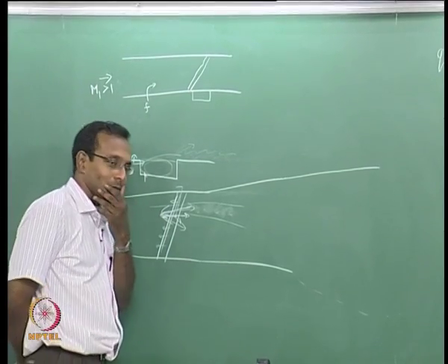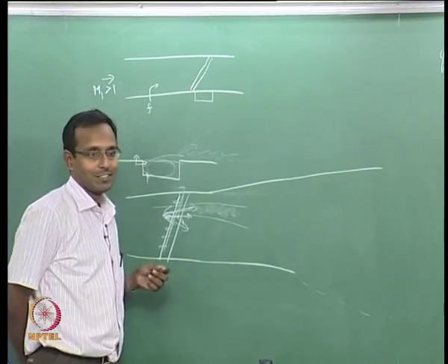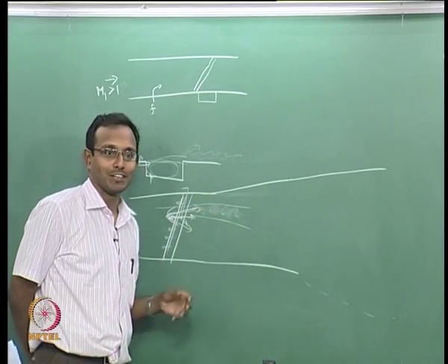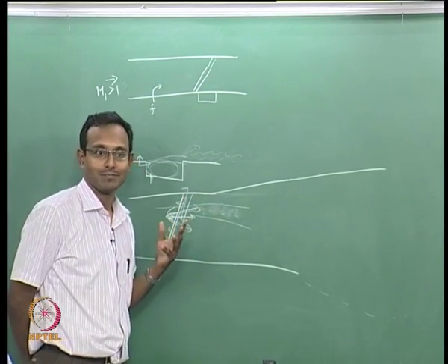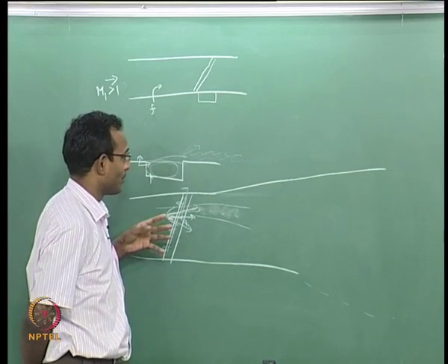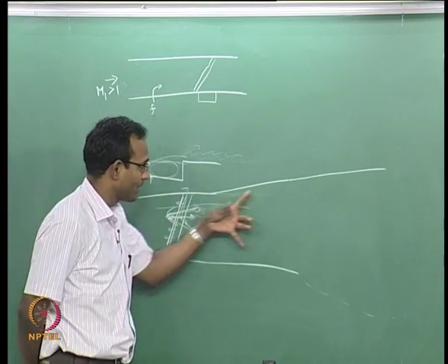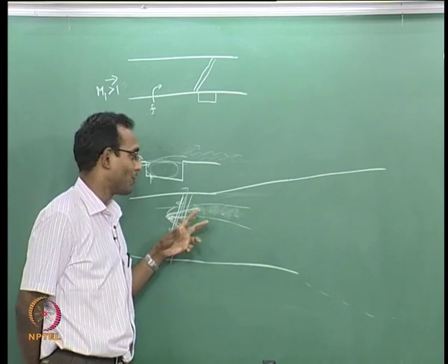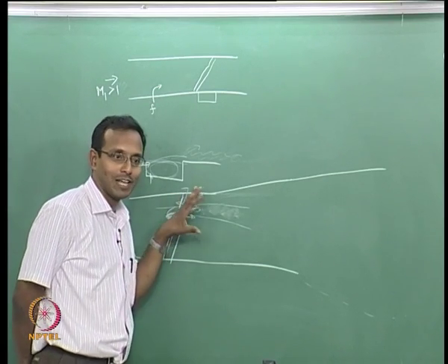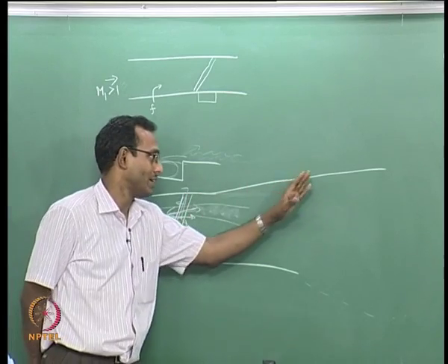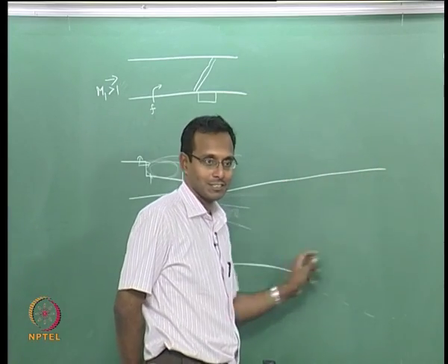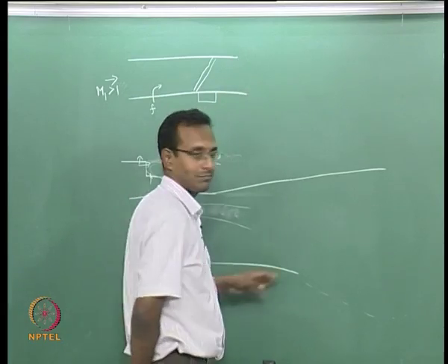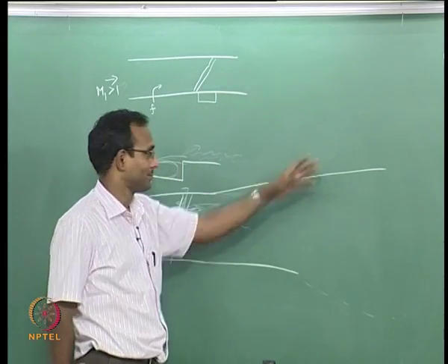There is one more problem with supersonic combustion, which is that the flow is going extremely fast and combustion is slow. So now I have to think about how the combustor should be long enough to release all the heat of the fuel before this fuel air mixture gets out of my area of interest, that is near my engine, near my scramjet if I think about it.